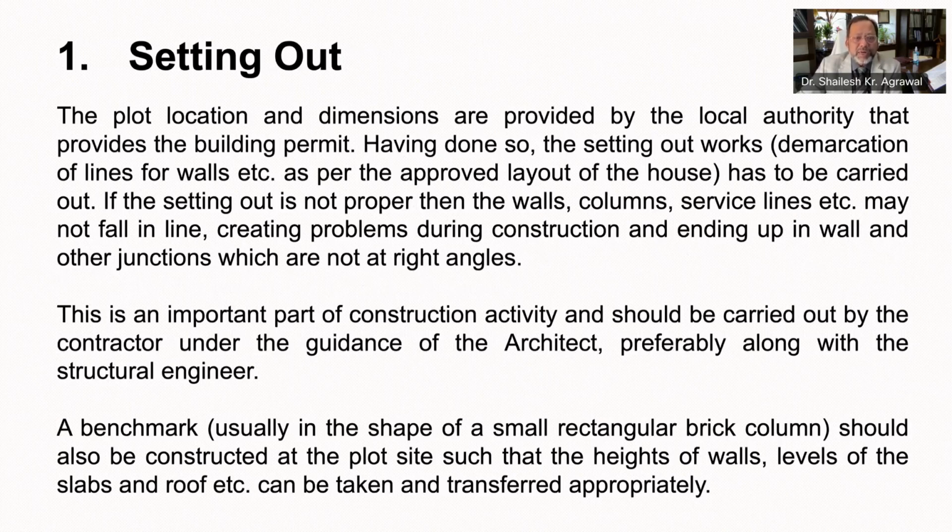This is very important and needs to be carried out by the contractor under strict supervision of an architect, engineer, and owner himself. Also, while setting out works, a benchmark should be constructed at a plot site. A benchmark is usually a small rectangular brick column which is constructed at a site such that the heights of walls, levels of slabs, and floors can be taken and transferred appropriately. Means benchmark helps you fixing the heights and levels of various elements and floors.